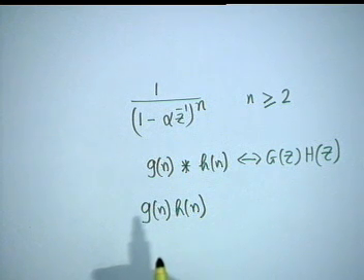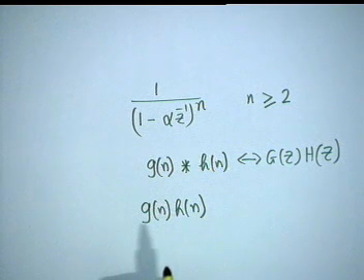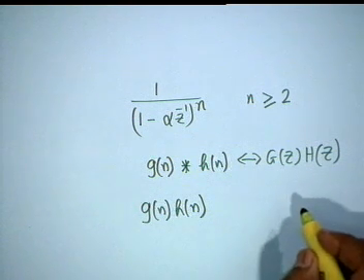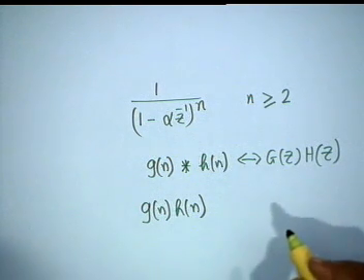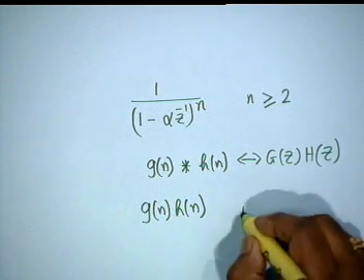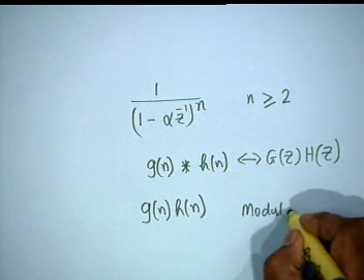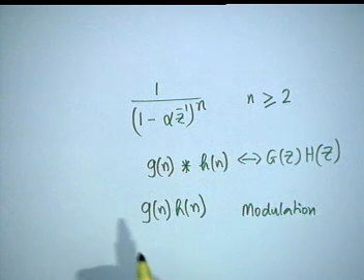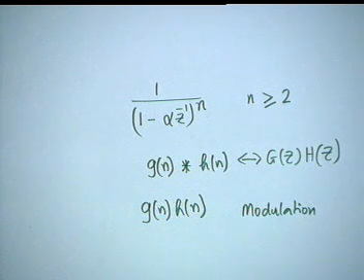And that is in terms of an integral containing a convolution of capital G and capital H, and a particular case of the modulation theorem in which small g and small h are identical to each other leads you to the Parseval's relationship for energy.